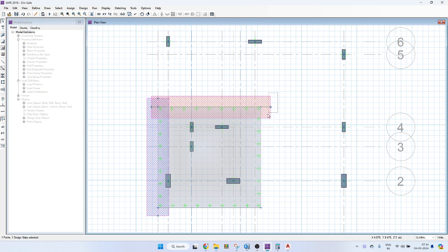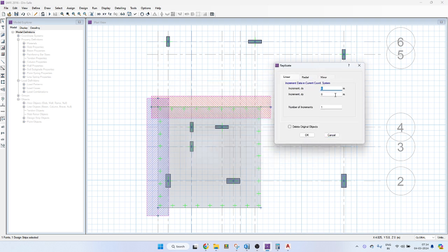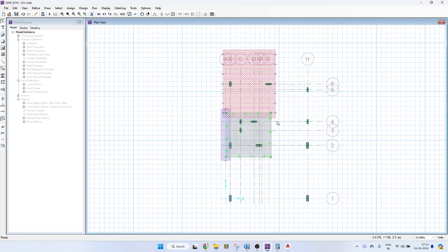But this is the line where it is going to cut. This is 1 meter. So this you need to put across this length. Linear, sorry, dy, this is because you have selected this one. It should be moving towards y, 1 meter. Number of increments will make it as 6. Some number you give. Oh no, it should have been -1.